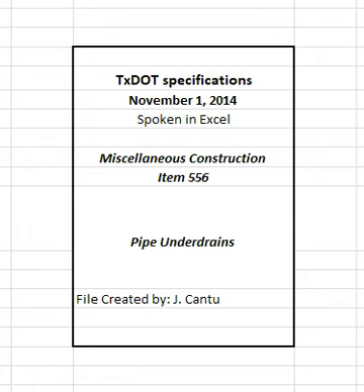5. Payment. The work performed and material furnished in accordance with this item and measured as provided under Measurement will be paid for at the unit price bid for pipe underdrains of the pipe type and size specified. This price is full compensation for pipe, couplers, plugs, screens, filter material, filter fabric, riprap, excavation, backfill, equipment, labor, materials, tools, and incidentals. Protection methods for excavations deeper than 5 feet will be measured and paid for in accordance with Item 402, Trench Excavation Protection.